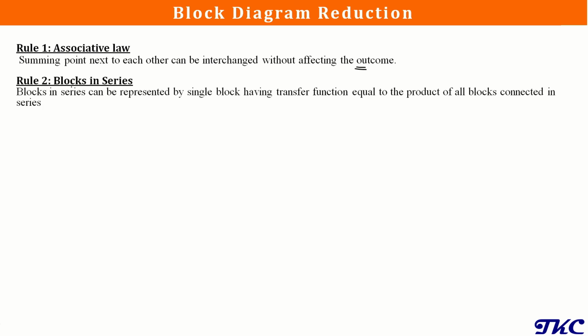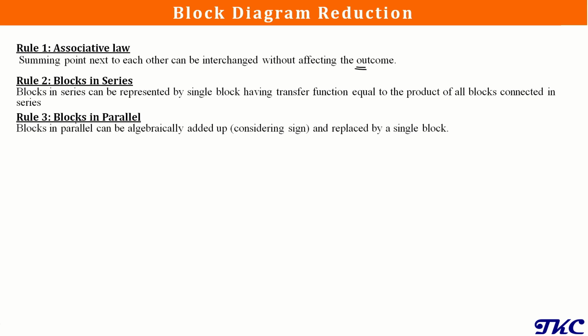Next is rule number 2, blocks in series. When we have a number of blocks connected in series, we can replace all those blocks with a single block, which will have an equivalent transfer function, which we get by multiplying the transfer functions of all the blocks. Next is rule number 3, blocks in parallel. So when we are having number